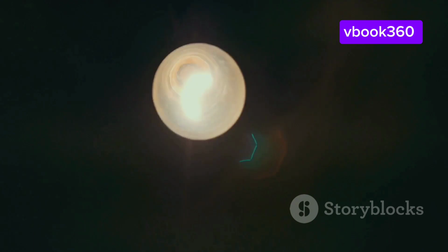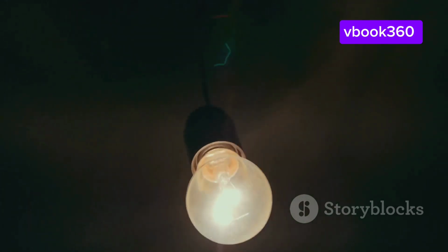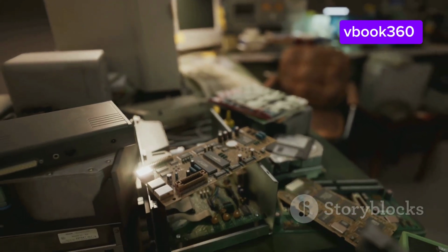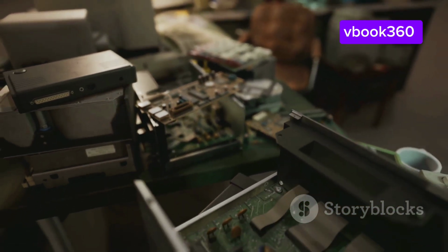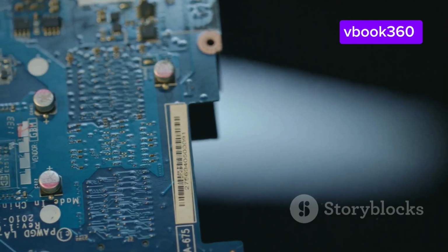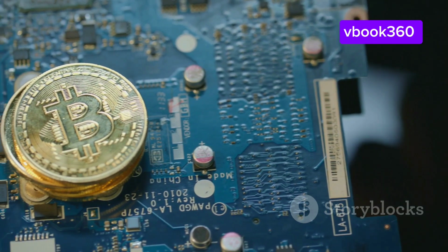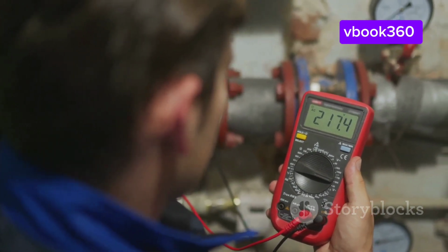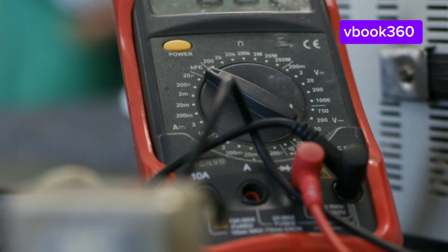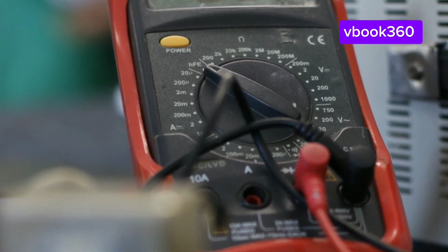Poor lighting. Trying to decipher resistor color codes under dim lighting can lead to misinterpreting colors, particularly similar shades like brown and red or blue and violet. Always ensure you have adequate lighting to distinguish the colors accurately. Color blindness. Some individuals experience difficulty differentiating certain colors, which can pose challenges when reading resistor color codes. If you have color blindness, consider using a multimeter to measure the resistance directly, or seek assistance from someone who can accurately identify the colors.